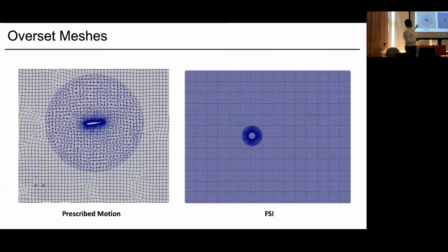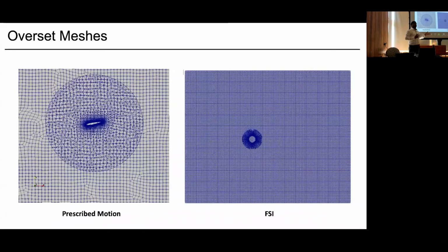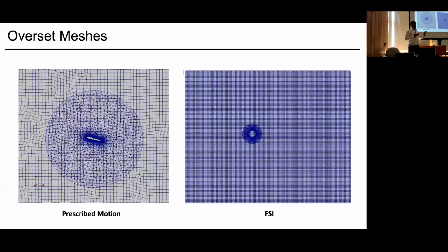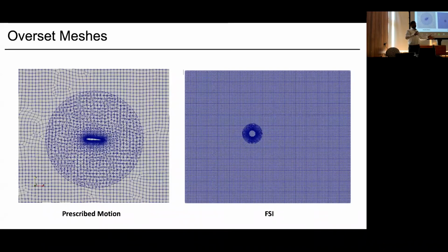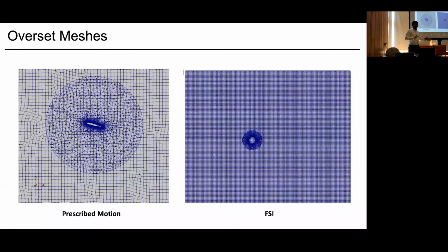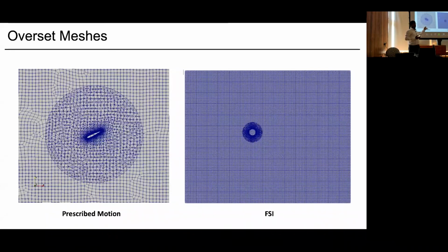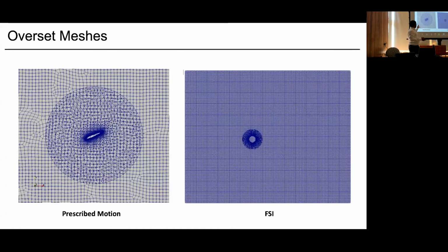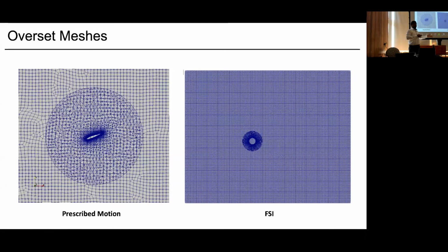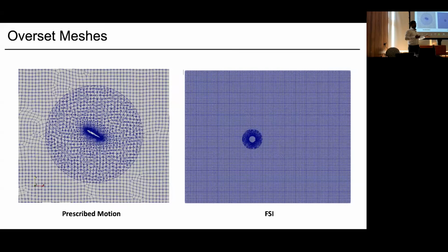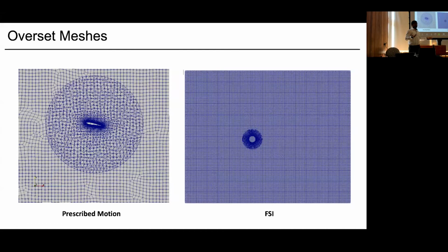Yeah, so in this particular case on the right side of my example, for the flapping airfoil, the meshes are generated in Fluent. It's very easy to generate unstructured meshes. The beauty of overset meshes is that any of these component meshes can be structured, unstructured, anything, as long as it meets your requirement, right? These two meshes are generated in Fluent, and I will share the link. This tutorial and the figure are taken from the training file freely available from Joel on his website, Wolf Dynamics, so you can download it. This is a Fluent mesh file which you can import in OpenFOAM with fluentMeshToFoam, right?